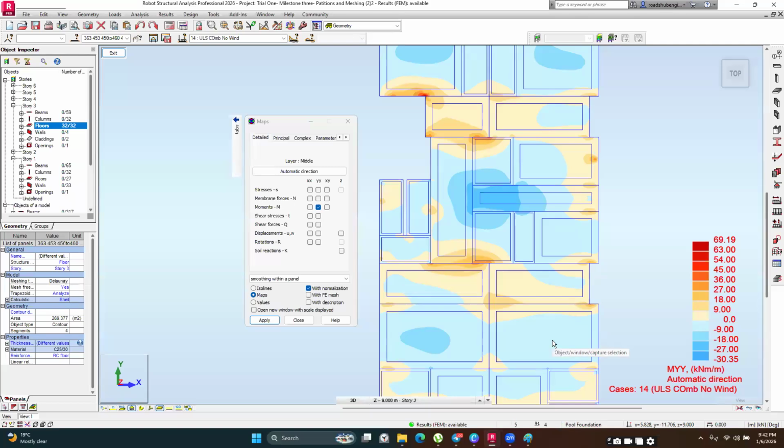When we get to the detailing part, you're going to see that you're going to be having top bars along these points here. And then typically for slabs, you do not have any top bars near the midpoints because you can see they are literally not needed. There are no top moments at these particular sections. And at these sections, bottom bars are rarely needed. Only that, from the Eurocode, when you're detailing your bars, they need to go to the support. Other than that, they are usually not needed at these particular sections.